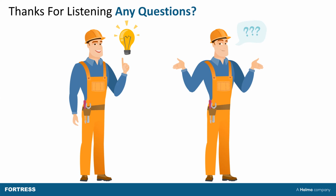of a control system. And they actually kind of come after this because you do your risk assessment, find all the risks, work out what needs to be reduced. You work out ways of reducing those risks using the devices and ideas that I've shown you today. And then if any of those are a safety related part of a control system, then you work out how much risk those specific parts are reducing, which will then give you the required reliability, which is your required performance level. A lot of people seem to think that you start with what your required performance level is, but really it's actually the last part.